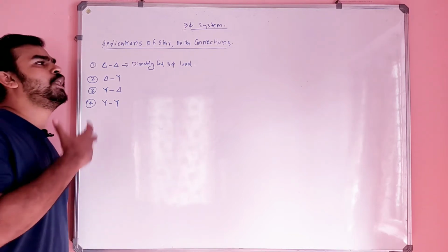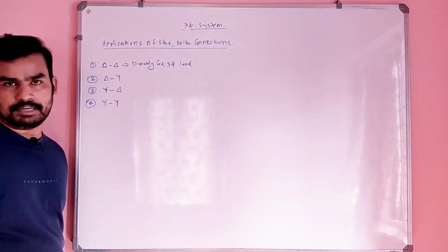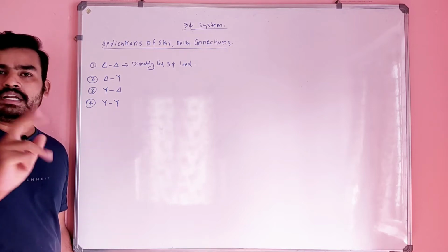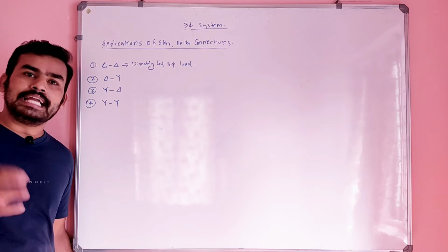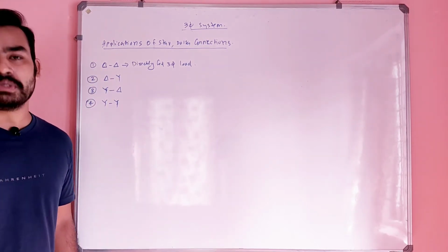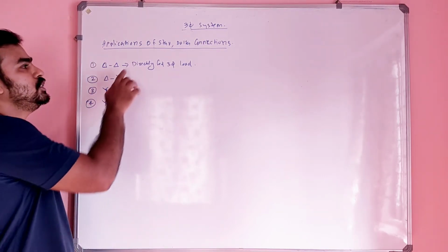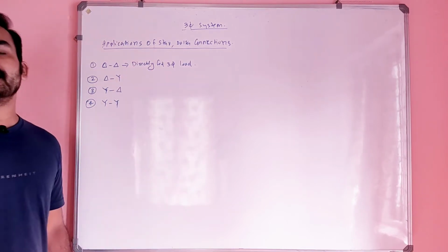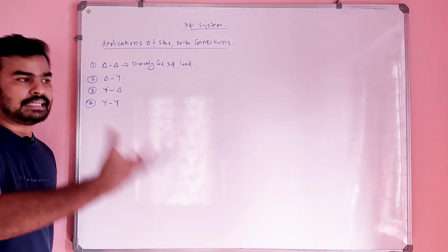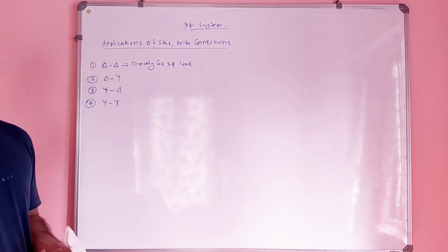A 3-phase load will have 3 terminals, so only a source which provides 3 terminals will satisfy that load. That source is nothing but a delta type source. That is why a delta to delta connection is used where there is a need of directly feeding a 3-phase load.